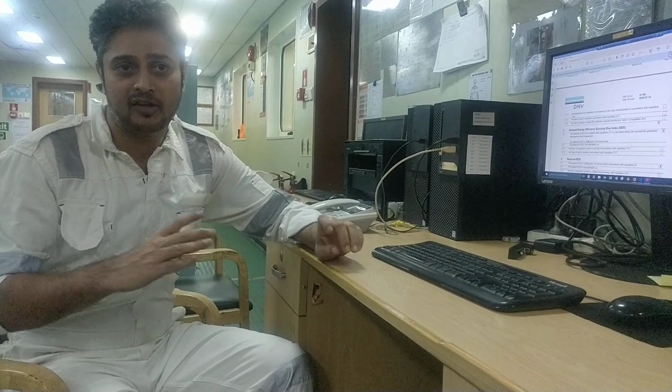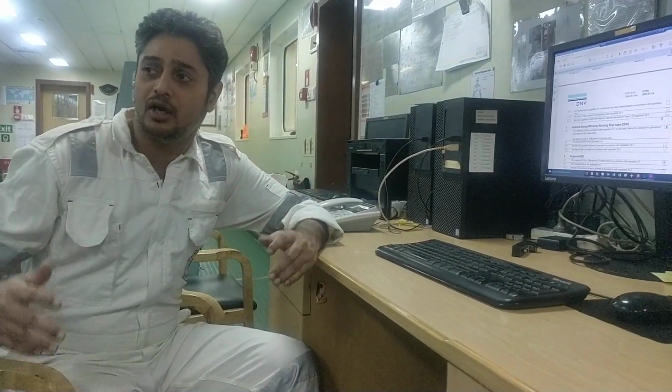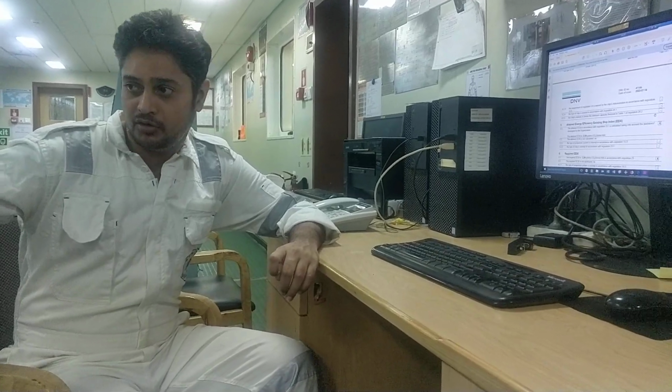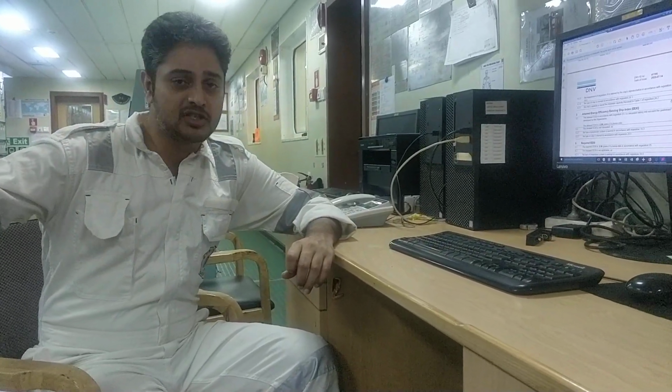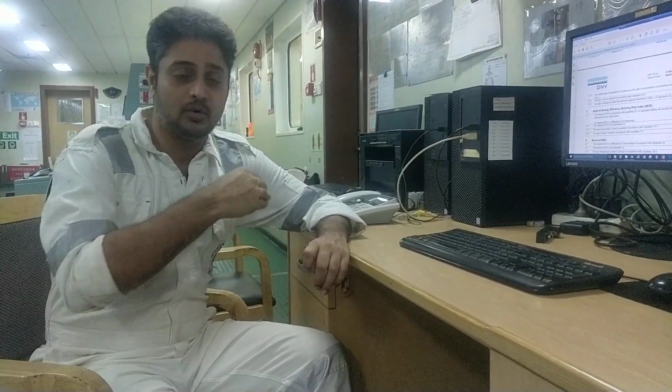So here now I will show you what all the documentation is which needs to be done. Once this setup has been completed, this wiring, usually how it went was, MAN will give you the instruction to set up the wiring. Before he attends the vessel, MAN gives from which junctions to connect the cable in the MPC and where you want to locate the EXA panel, in the sense the switch and the indicator lamp constitute the EXA panel.